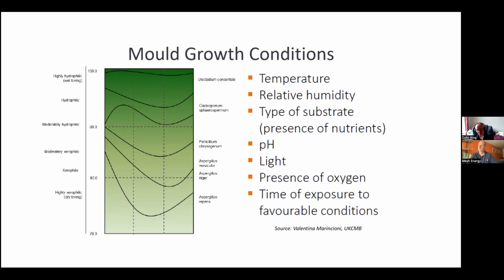The background moves more than the outside does, so it becomes a rigid fascia on that wall. The water gets behind it, it's then isolated from wind drying and solar gain. It falls, it fails. The pointing comes off, and somebody comes along, oh, I'll do that for you. I'll give you a nice strong new pointing of it. Whereas what you actually need to do is rake it out to a reasonable depth and reproduce it in a lime that is suitable for the substrate.